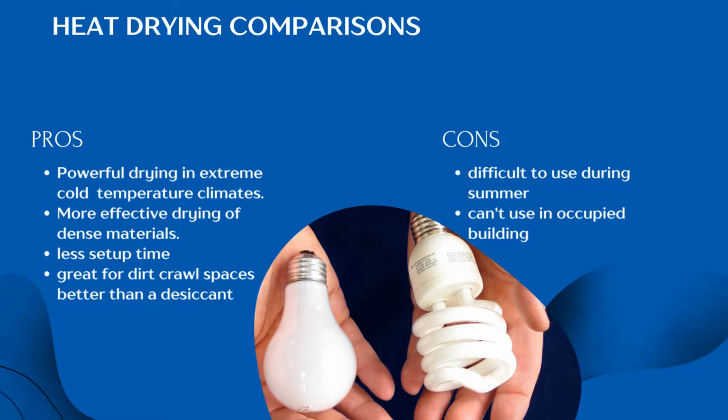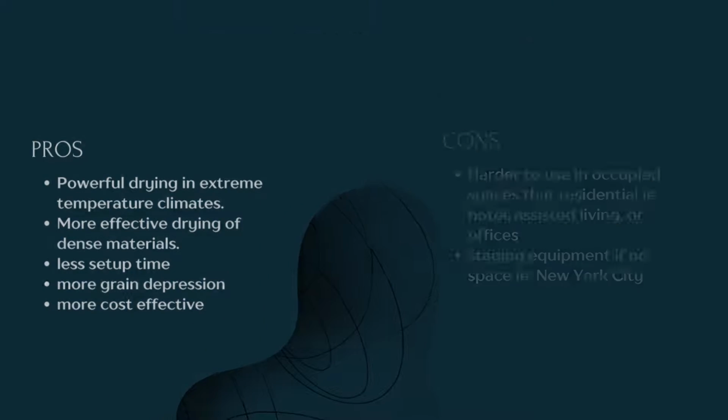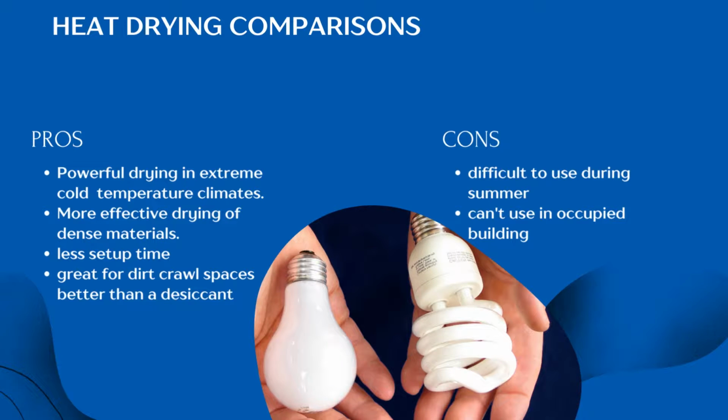So you have to take out what you're putting in. So you have to vent that heat out a window, out a door. You may have to put negative air machines in to pull that out. Use your gauges so you can tell not only your pressure differentials, but how many CFM you're blowing in and out of the building, so you can keep that as neutral as you can. But still, a really good tool to be able to use is in the heat drying.